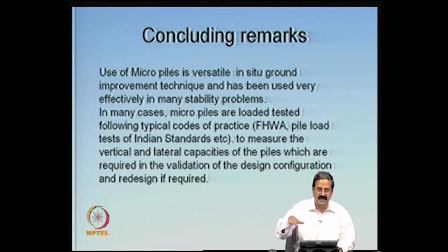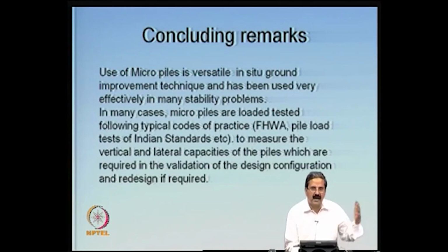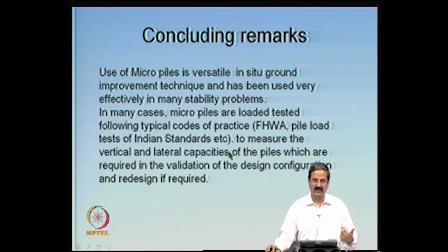So, we do a pile load test and calculate both the skin friction and shaft friction, and once you know that for this length of pile the design is correct, you can even modify the design. The same thing applies to lateral capacities. In the particular case in the northeast, the lateral force required was quite high because it had to be designed for earthquake conditions, when the lateral force resisted will be higher. So, you must be able to design for the lateral force also. You may design, but then you should check.